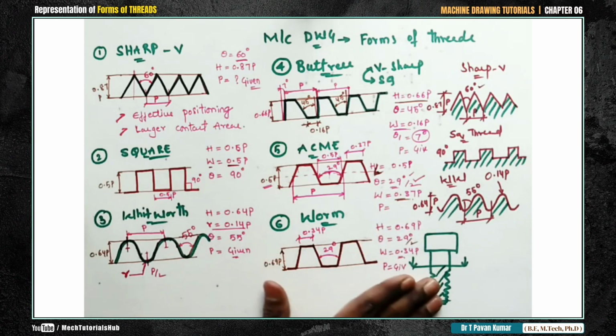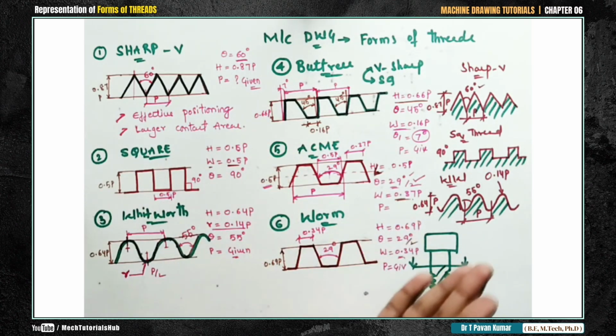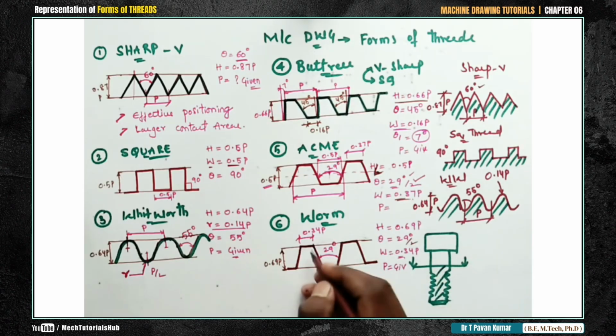Now as I am drawing with my free hand, I could manage. Now try to consider some offset distance with a 2H line. Try to match up all the lines with this particular baseline, okay. 1 2 3 4 5 6. There is no count actually. For my understanding, I am doing it. There won't be any count, okay. You will get proper alignment. That is the reason we will take the baseline, okay.